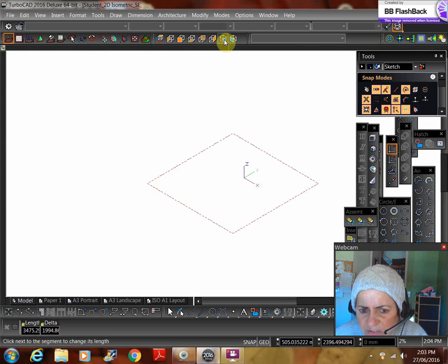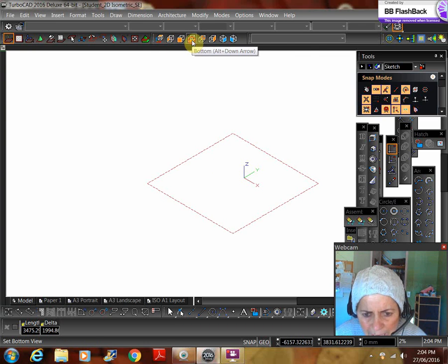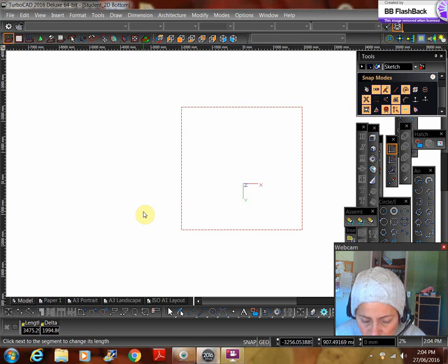And if I click on isometric view, you see this dash line, like a trapezium here, is a work plane. Similarly, the sketch and model are best viewed from an isometric viewpoint when extruding objects to create a 3-dimensional solid. So when I clicked isometric view, this shape came. If I click this bottom one, that is work plane, it shows a different one, 2-dimensional.